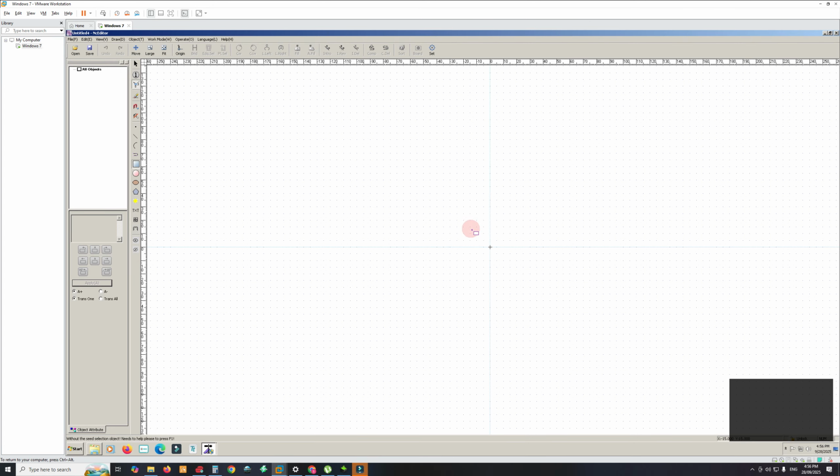New file, we will just give you the layout of NC Studio. Over here on the left hand side, I call this the polyline browser. It shows you all objects that you've made and enables you to tick the box and select them, also to delete them, all sorts of stuff there, and I'll go through that a bit further later on. Down here we have the dimensions window. There's no dimensions there because we haven't drawn anything yet.